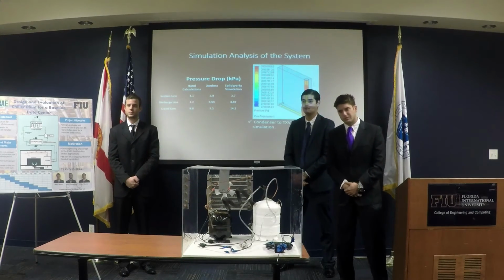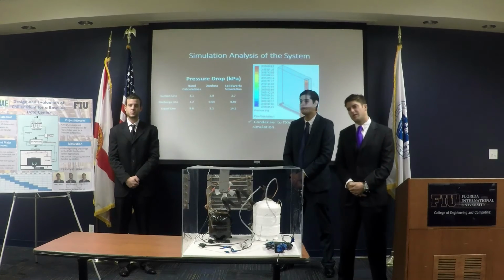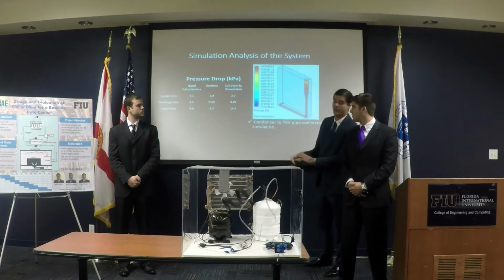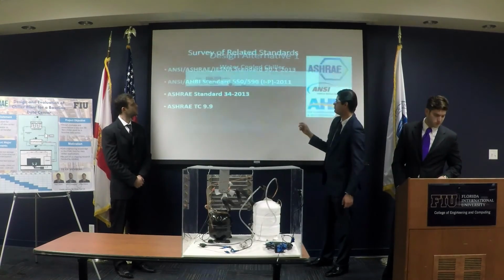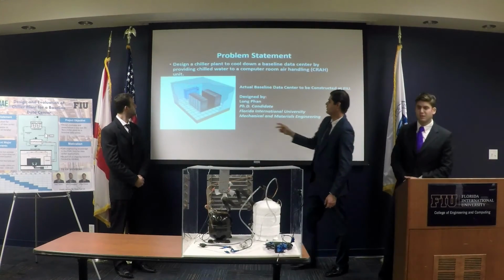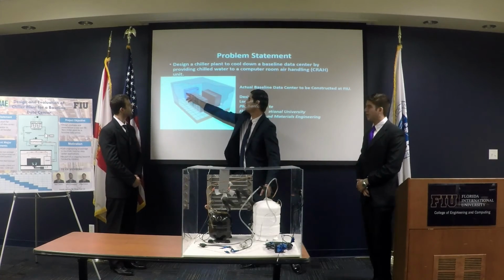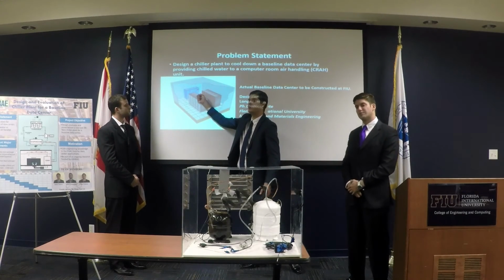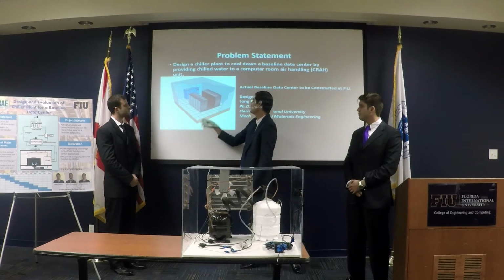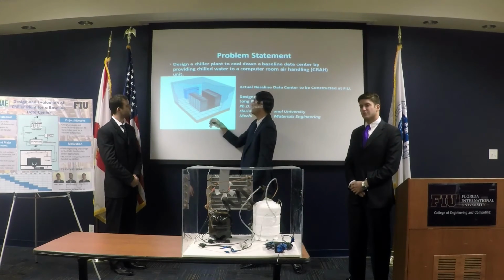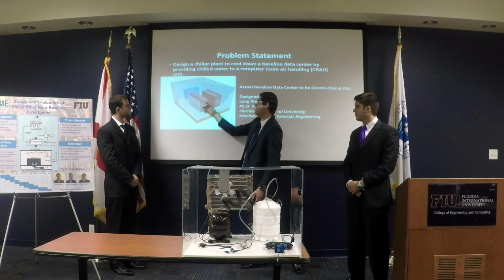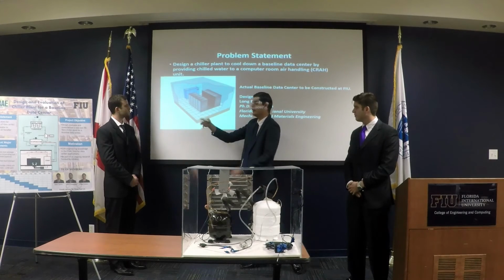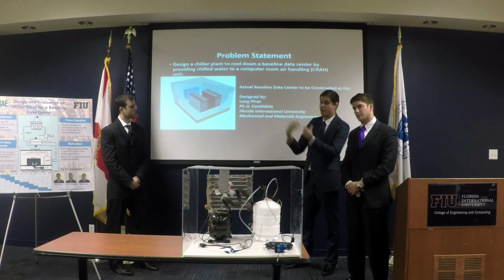So you don't know the square size of the building or the heat that was generated by the computers? We have an image of the design of the data center. This is the design, this is the CRAC unit, this is what will be receiving the cold water and providing cold air. And these are the racks. The way you do this calculation is to take into account every heat source, and by adding the power ratings, you get that number. But that number was given to us.